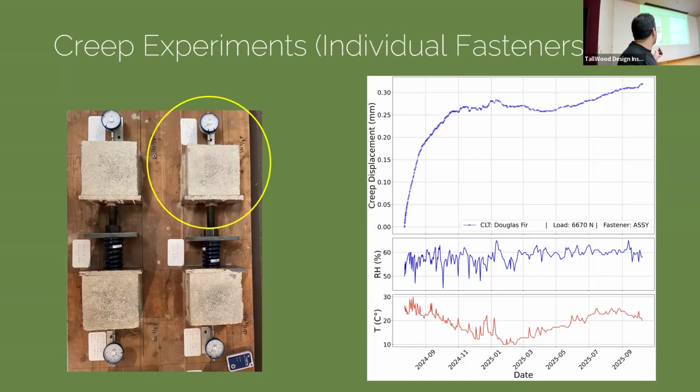And we have the dial gauges, and we are tracking the long-term deformation. So I have a year of data. The first data belongs to July last year, and I just took the picture for the last data a week ago. It's still ongoing. So I have about 40,000 images right now. So this is just the creep data. You can see the different trends. I believe this is because of the seasonal effects.